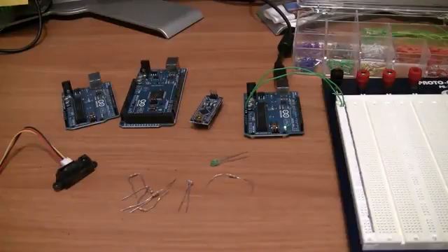You can set the reference voltage that you use for the analog inputs on all these Arduino boards. By default, it's set to 5 volts or 3.3 volts on 3.3 volt Arduino boards, but here we'll just be working with the default 5 volt boards. You can also set it to an internal 1.1 volt reference, although that's not available on the Mega. And on the Mega, you can use different commands to set it to 1.1 volts or 2.56 volts as a reference. You can also set your own voltage reference by setting it to an external value, which you input into an analog pin on the Arduino.